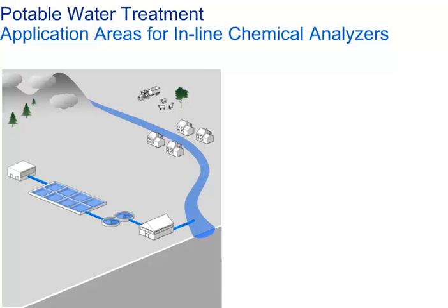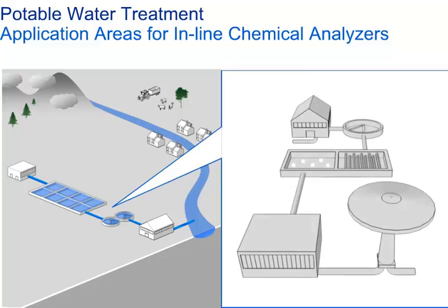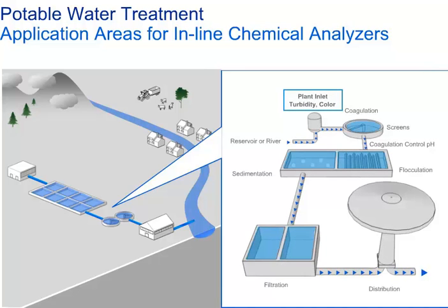If we take the example coagulation control, each plant in each region will vary based on the amount of contaminants entering the plant. Several points of measurement are located throughout the plant, which include measurements like turbidity, color, which allow proper control in the coagulation bed and settlement tanks. Also, measurements are taken after the process to ensure that the final product is clean.